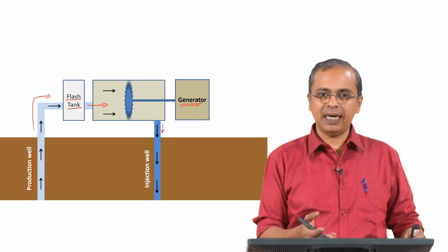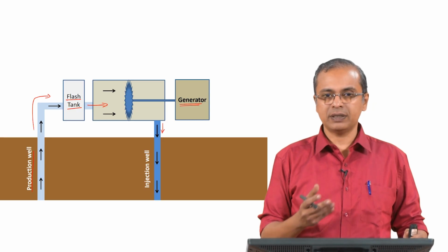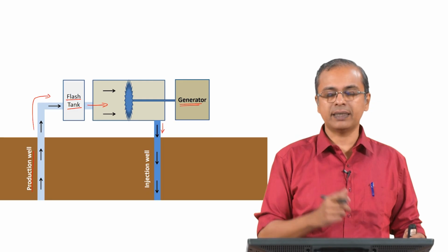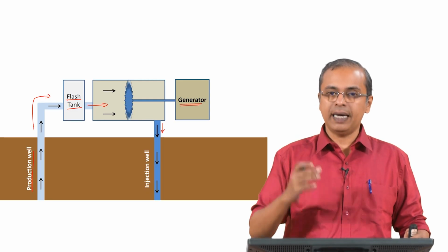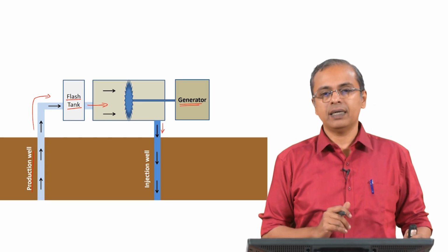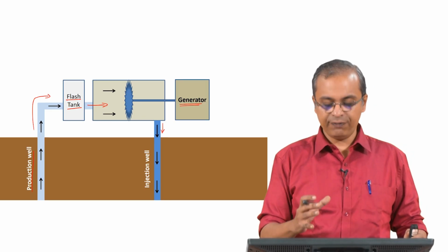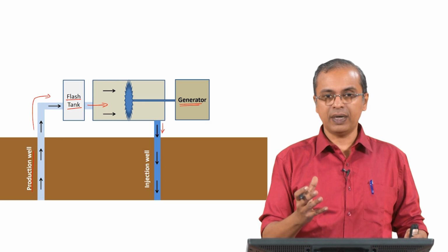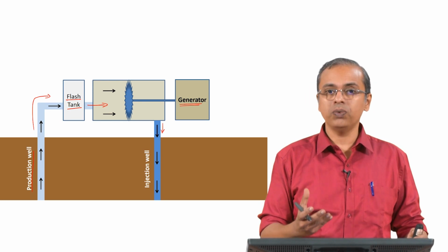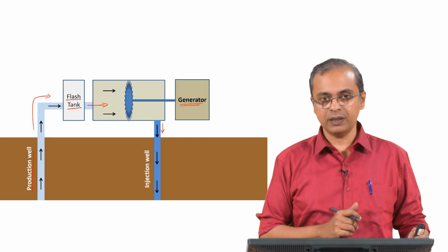And again, it depends. If it is still in steam condition, you can again put a condenser and drop it to vacuum conditions, get the liquid water to form, and then you can send that liquid water down the injection well. So, this is the manner in which you would handle a situation where you have saturated steam becoming available to you from the location where you have done this prospecting.